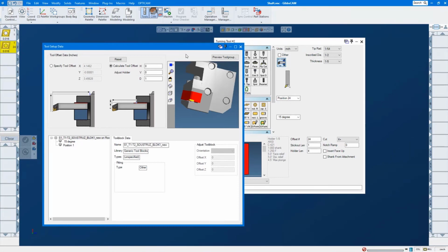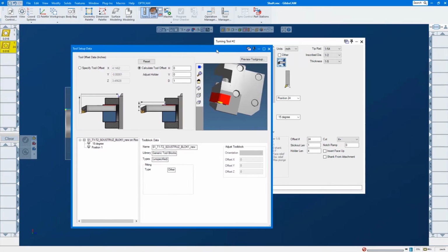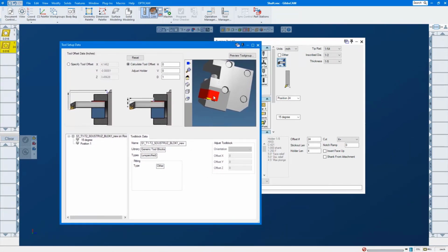Now, with that said, what I found was if you don't set this up right, and a lot of times what will happen is, and I've done this myself 100 times, you should put it in there, and I test it always on a 2-axis lathe. If you test this on a 2-axis lathe, it will tell you right away if you're set up properly, because on a 2-axis lathe, it'll come back and it'll say, hey, the tool didn't reach its position. And that's the clue right there that, hey, something is not at 0.